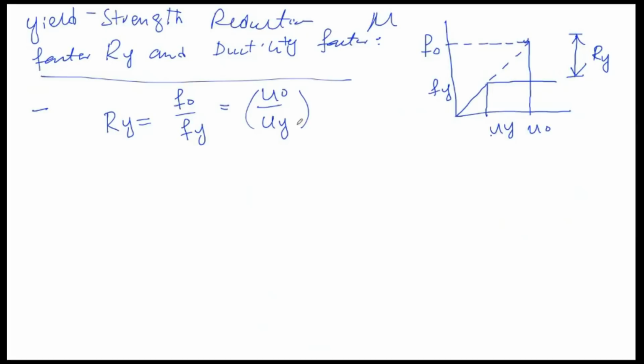The peak deformation, or the absolute maximum deformation, which is here, for example, when the system gets yielded, now there is another deformation that will take place, that is represented by the peak deformation or the absolute maximum deformation um, which is that of the inelastic system due to the ground motion. Now, the ductility factor that we talk about is basically equal to this inelastic displacement divided by the yield displacement uy.